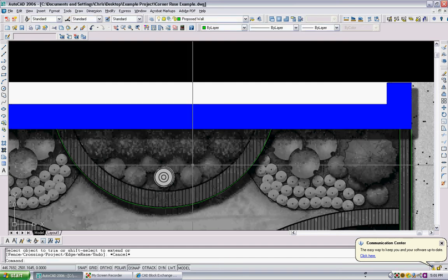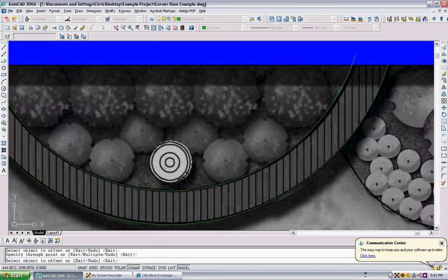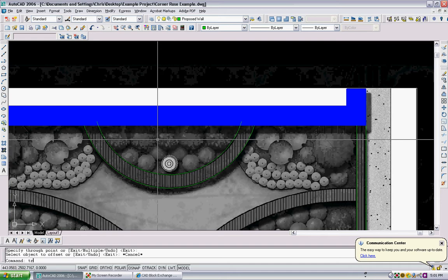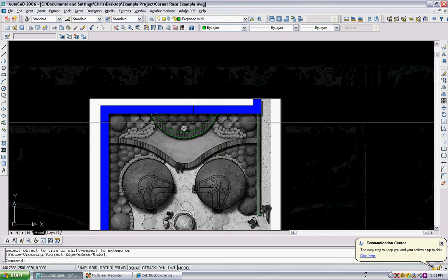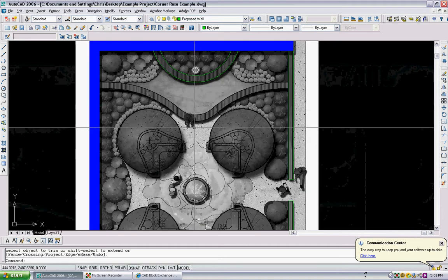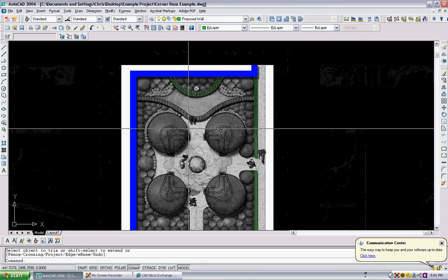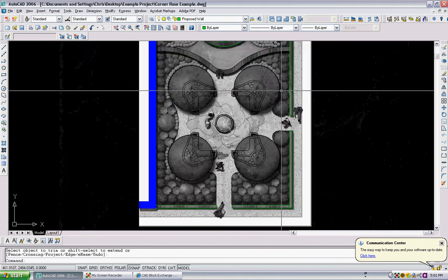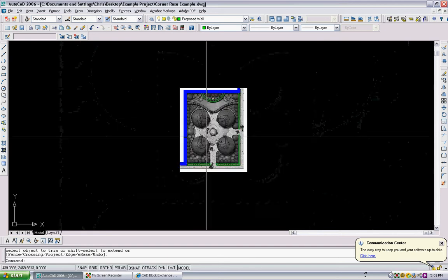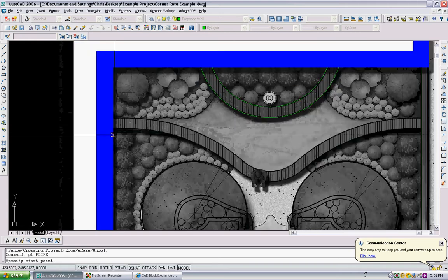Trim that. Then I'm going to offset through. So you got that second wall. Let me trim that again. Okay. And now the second part, I'm actually going to do half of this wall, and then I'm going to mirror the rest of it. And you'll see how powerful the mirror tool can be. Especially when we'll do one of these and we'll mirror it, and then we'll mirror that again, those two, and it makes things a lot quicker. So let me get this one started.